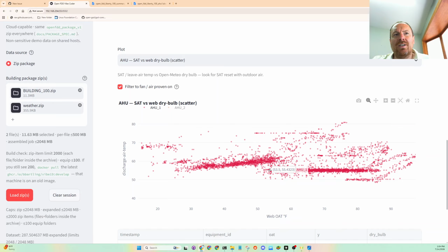They do something kind of funny. It's not a bad thing to lock it in at 55 degrees, especially in this building's location. Very humid, and 55 degrees Fahrenheit is a very common design cooling parameter used for air handling units. Except usually you don't need 55 degrees until way up here when it's warm outside.